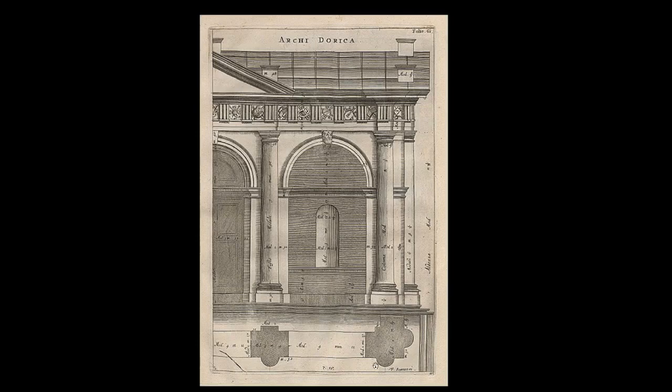And then here you see in the ground floor plan also that it's more like a half column, so it actually just indicates the proportion. It doesn't really carry any load, so the wall itself is already carrying the vertical loads, and the arc functions as a window or opening.